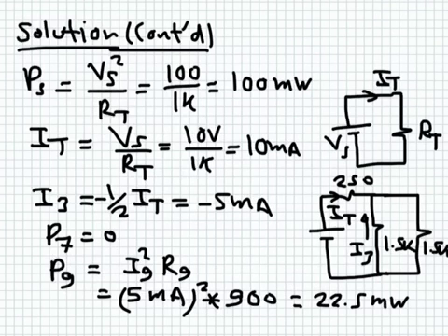So we have already calculated the total input resistance, 1 kilo ohm. We have one source, it's 10 volts. We know the power delivered by the source. It is the source voltage squared divided by the equivalent resistance. So 100 divided by 1 kilo ohm will give us 100 milliwatts, or 0.1 watts. We know the total current flowing in because I know that the source is 10 volts and the total input resistance is 1 kilo ohm, so 10 volts by 1 kilo ohm, again 10 milliampere.